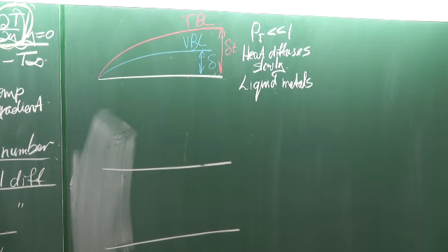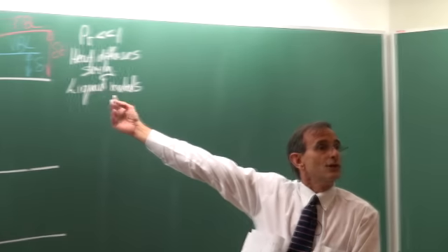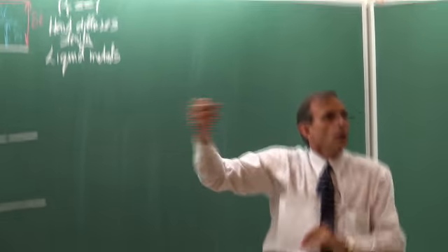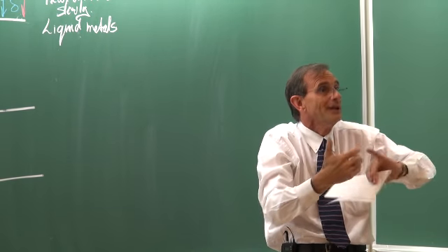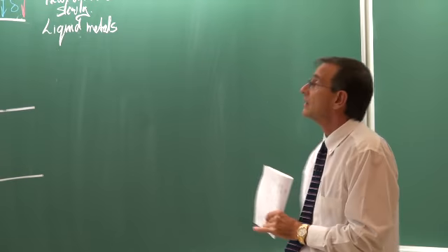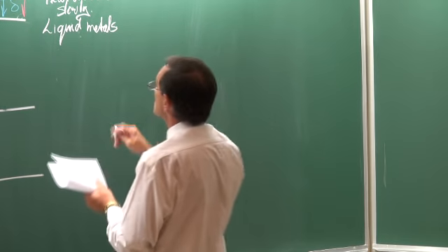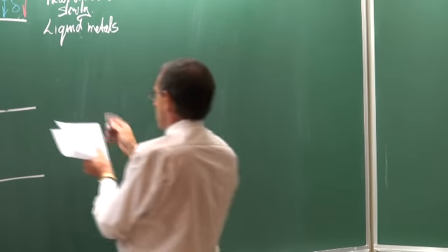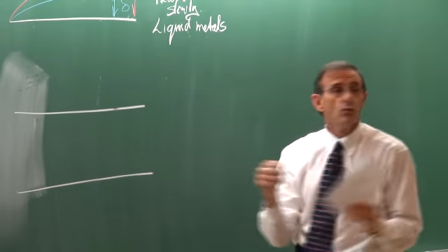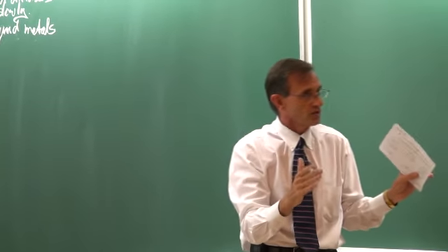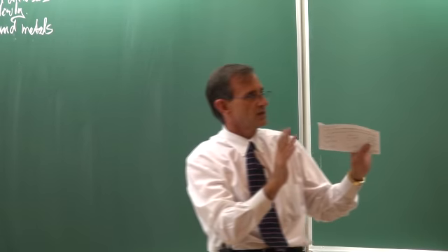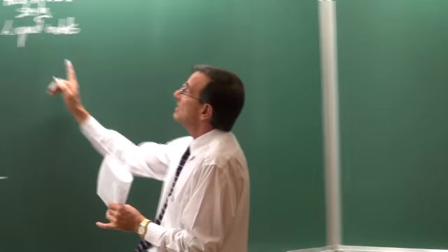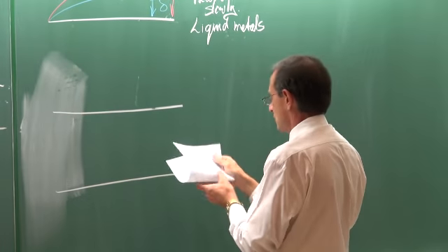And why would we use liquid metals in heat transfer? Well, they are used in nuclear reactors, for example, where there are small surface areas and lots of heat that needs to be transferred. So the heat diffuses slowly with liquid metals, and the problem with liquid metals is that they are very corrosive. That is why we do not normally want to use them, except in very, very specialized cases. So that is the one possibility.